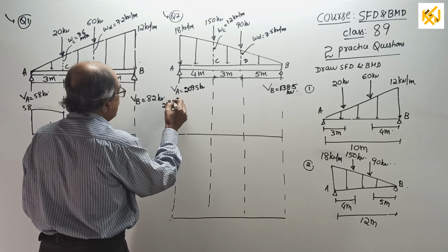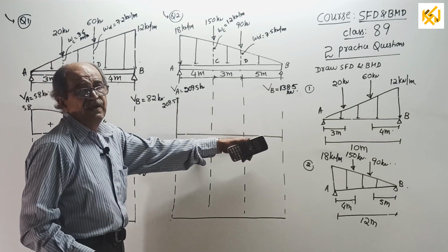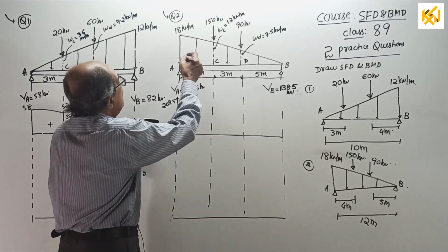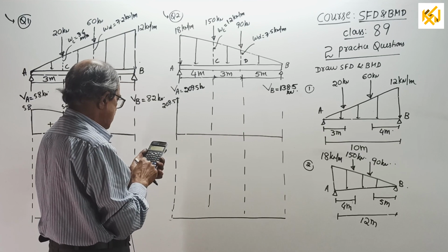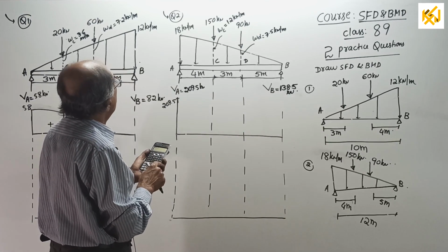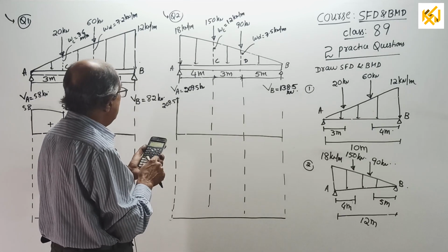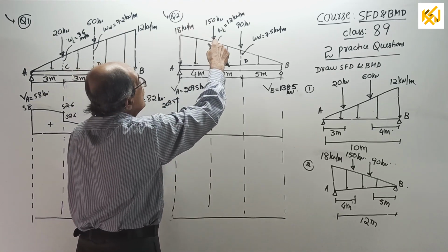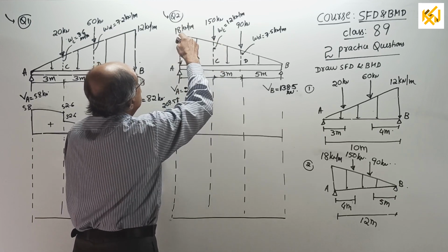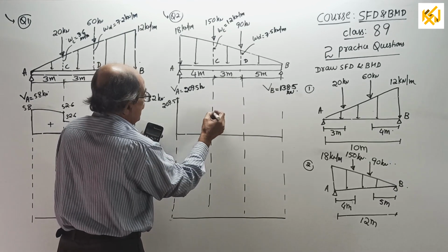You solve both separately, not this way. As you finish this one, you start this one. Then come to bending moment diagram. Here to here. Come down by this much load. So, 209.5 minus 18 plus 12 divided by 2 into 4. And remember here, intensity is maximum. Here, lesser. So, here, more slope, lesser slope. The value will be 149.5, somewhere here.